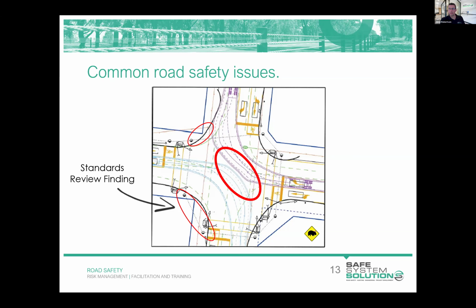You then need to think about the issues associated with vehicles doing what we can see on the screen, or potentially coming into conflict. That's our job as an auditor, to assess that risk and come up with some mitigations. One of those would be to pull a hold line back. You can see a slight cutting across of the hold line here. You could pull this hold line back, push it further to the north to fix that situation.